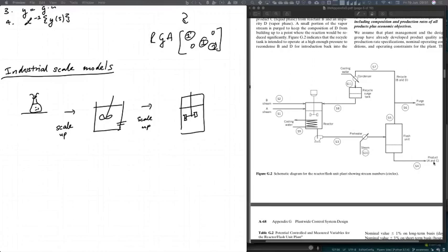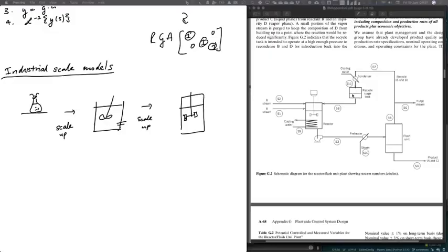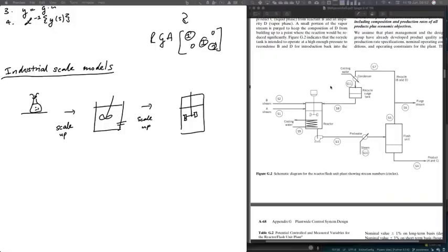But if I have a very strong recycle stream, and if I'm using that for control, I may introduce fluctuations by manipulating this recycle stream. And that makes it harder to reason about how the system behaves. And so instead, I will not manipulate the recycle stream. I will rather keep that recycle constant, for instance, and make sure that by doing that, if I keep this flow as constant as possible, I'm reducing that recycle effect.